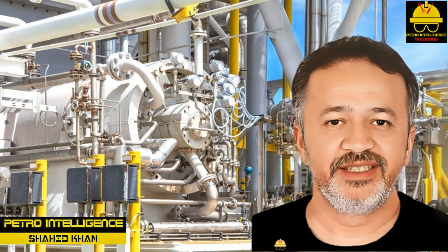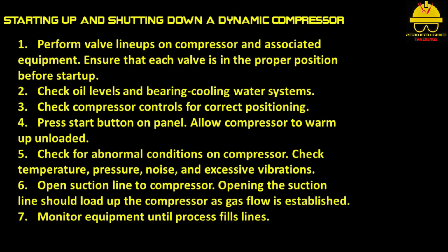Starting up and shutting down a dynamic compressor. 1. Perform valve lineups on compressor and associated equipment. Ensure that each valve is in the proper position before startup. 2. Check oil levels and bearing cooling water systems. 3. Check compressor controls for correct positioning.